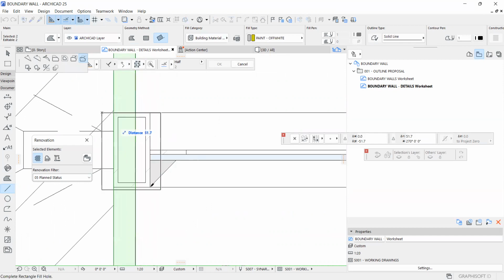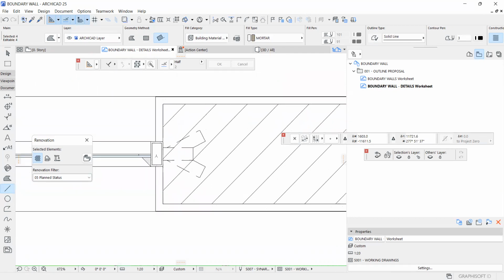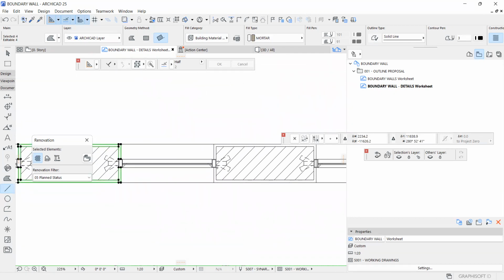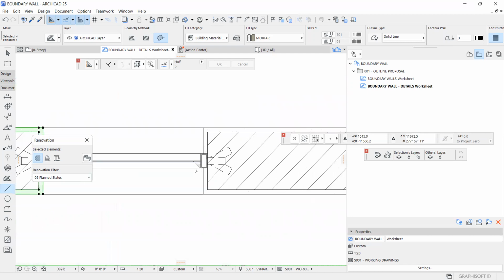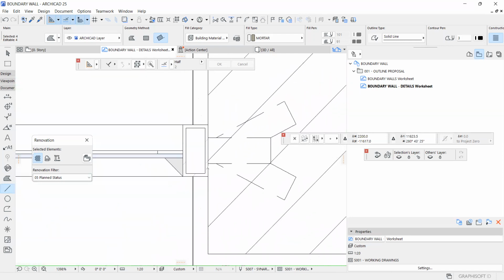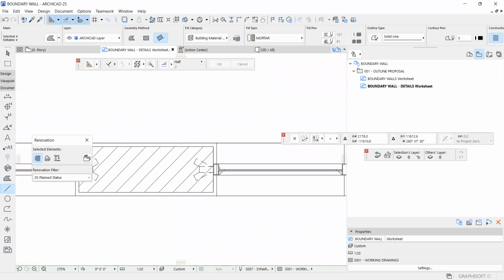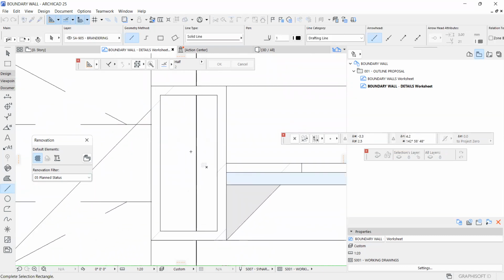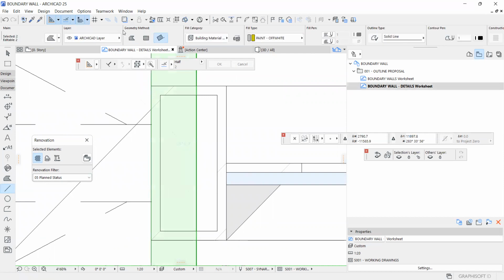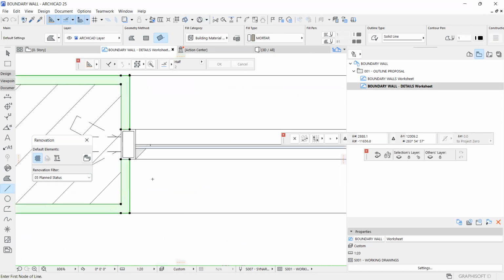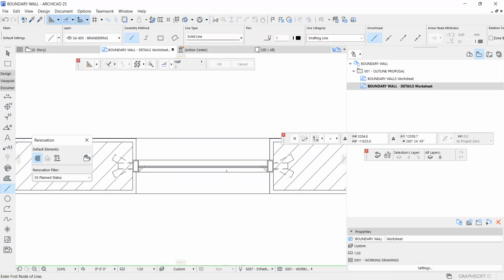Priorities are usually dictated by the precedences during construction. What comes before the other? I cannot paint before I plaster. I cannot plaster before I fix my window. So if you have a proper understanding of this process, then it becomes very easy. That's why I always insist that you must learn the construction processes, all the step-by-step processes in construction.